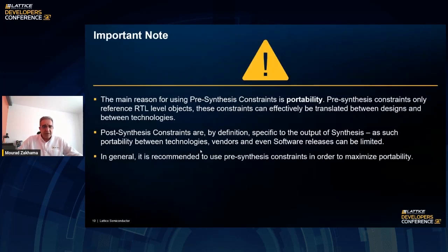So an important note, I think I alluded to this in the previous slide. The main reason for using pre-synthesis constraints is portability. The timing constraints only relate to the source code, and they can obviously be transferred between different device families and different vendors. You can use them without having to change them every time.